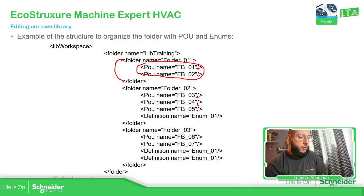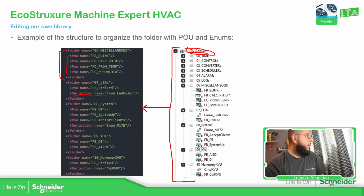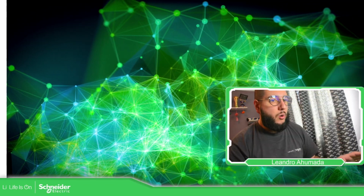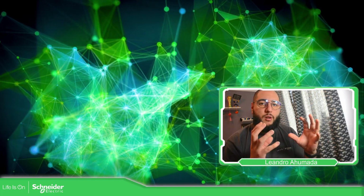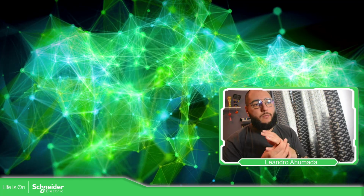So it's important to follow the syntax, otherwise you see what happened. So in my case, you just need to check the syntax. I forgot to use this one, and the software didn't recognize the library. Okay, so you need to make sure about that. You need to open the folder, close the folder, assign the POUs that you want, or the enumerations using this enum. The function block or enum must be between this part. Here I forgot to use this. But here you can see the syntax is correct on the enum. So it's easy to just take time to organize the data. So this is how we can configure and organize the library look and feel once we export the different POUs, function blocks, functions into our library.